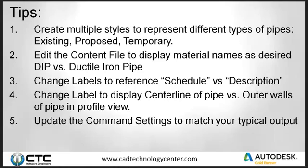The other solution is, if you still want to maintain the double line, just go into that setting for that pipe style and turn off pipe ends. Then you'll still see every kink, but you won't see where the pipe splits every 20 feet.